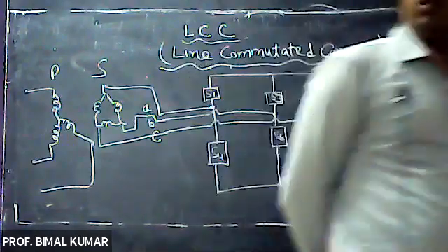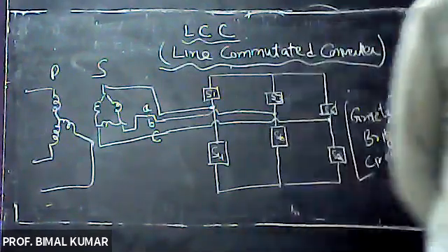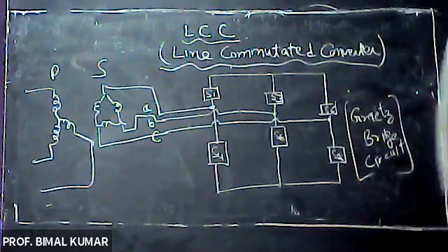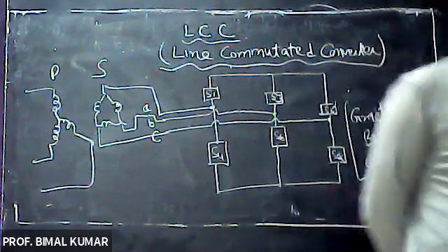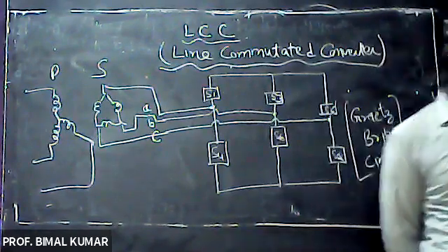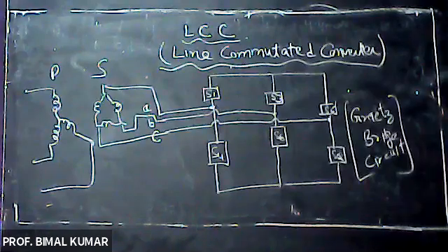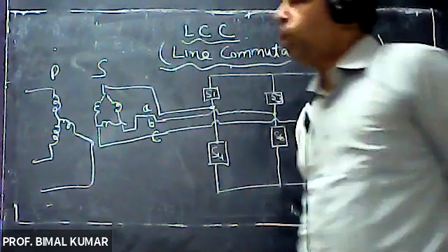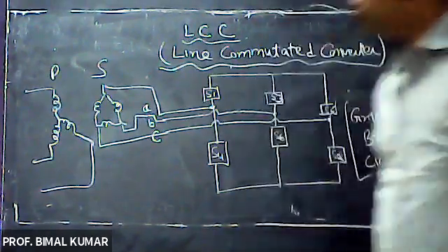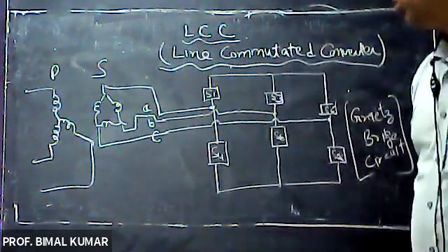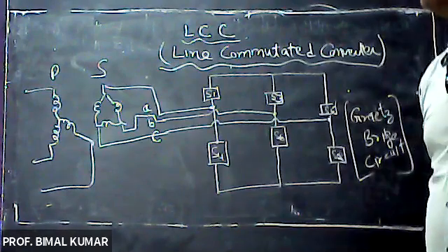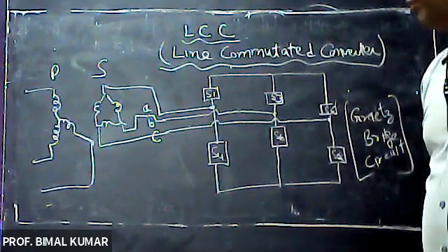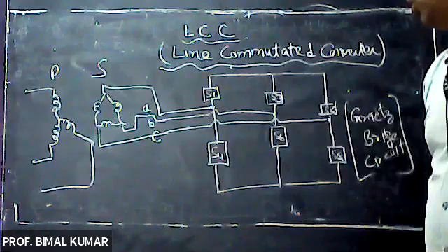Now, about the other two purposes: the first is voltage transformation between the AC and DC side, and the second is adjustment of the applied AC voltage by OLTC, right? Both of these purposes may be solved with the help of an auto transformer.